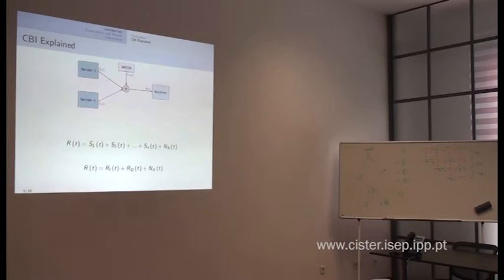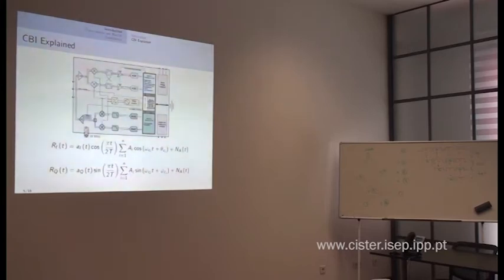If we go back to the model, let's rewrite our received signal, which we call the composite signal. You see this is a superposition, and we're going to split it into in-phase and out-of-phase components. This is what we get, and we're going to focus now on the receiver. This is what we have at the antenna of the receiver: these two signals, in-phase and out-of-phase.